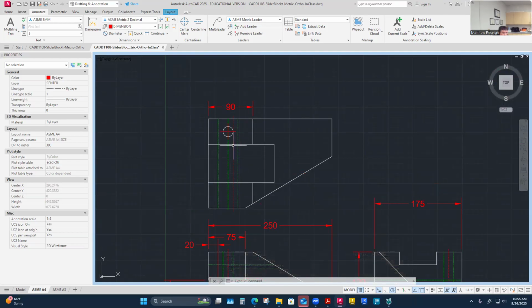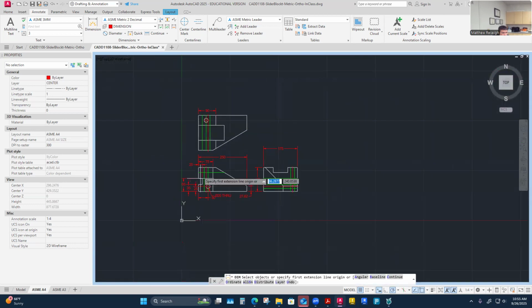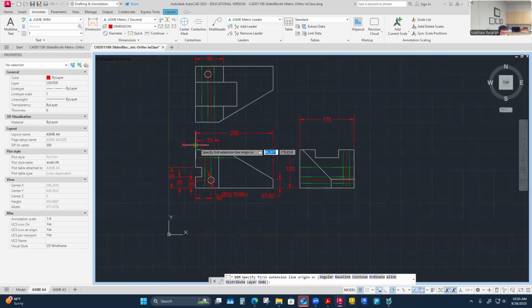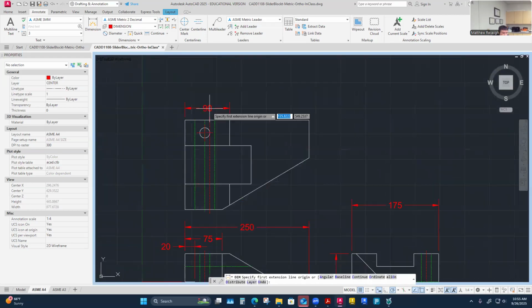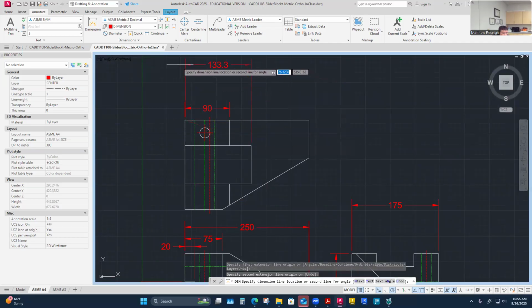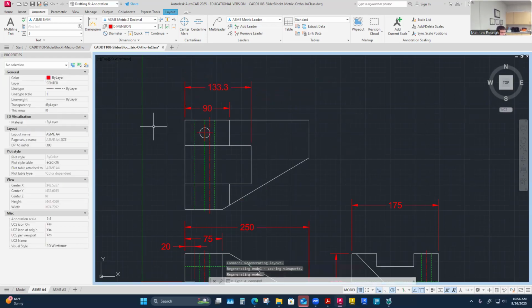I've determined I don't have this. It might be a nice to know, so I could add that. This is still a good dimension because I'm really pulling from that left side datum. You can see that the surface that appears as a line here is definitely a great place to pull dimensions. I'm pulling another one here. I'm really pulling from the same datum from the front view to the top view, using the same surface where it appears as a line.